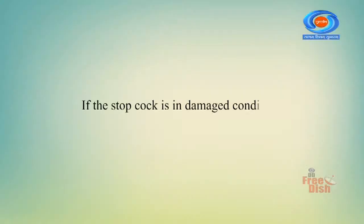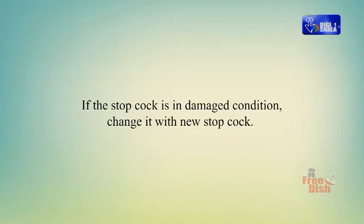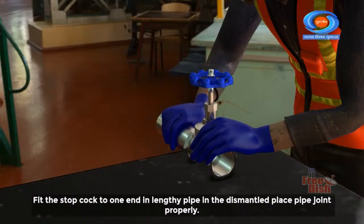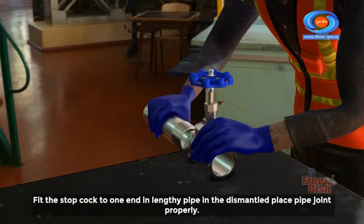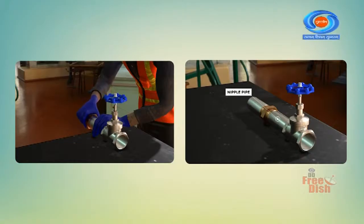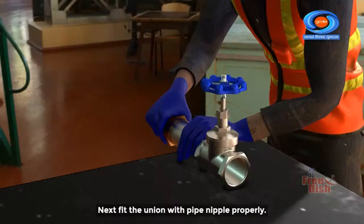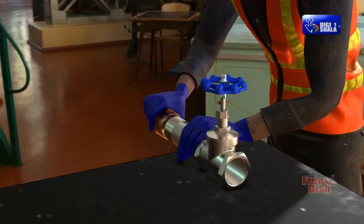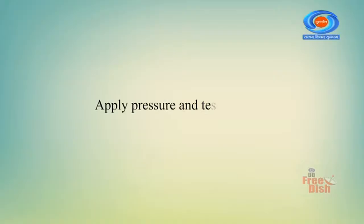If the stopcock is in damaged condition, change it with a new stopcock. Fit the stopcock to one end of the lengthy pipe in the dismantled place, and join the pipe properly. Fix the pipe nipple to the other end of the stopcock properly. Next, fit the union with the pipe nipple properly. Apply pressure and test the pipe joints and stopcock. Check for leakage, if any, to ensure proper working.